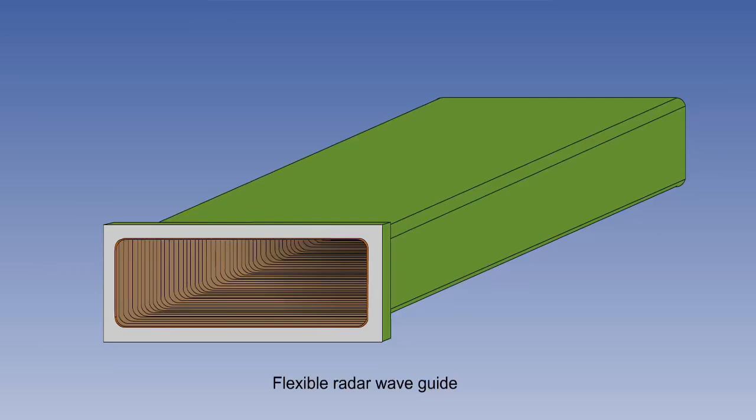Because of the power required for these systems, waveguides are used rather than cables to carry the energy to and from the antenna. These are tubes or boxes, half wavelength in width, along which the energy zigzags. The waveguides may contain air which may be pressurized, or they may contain a vacuum.